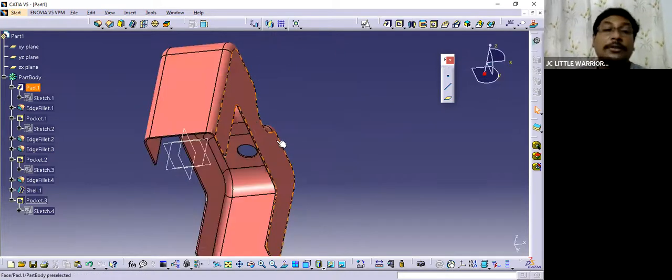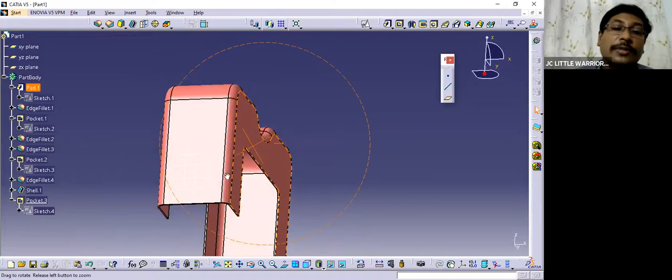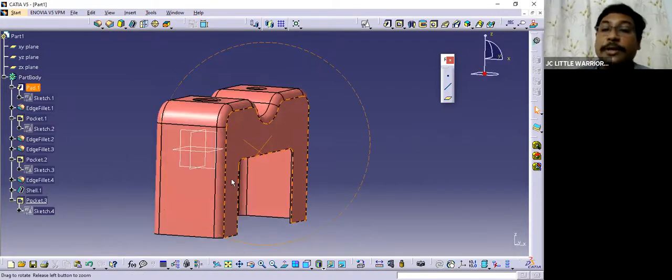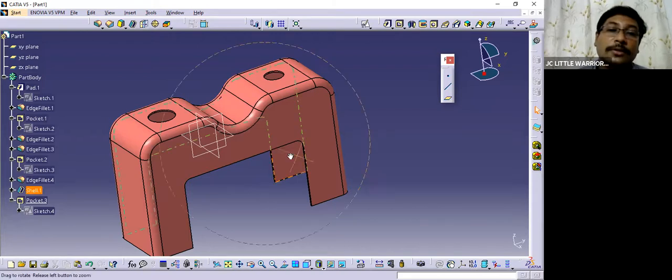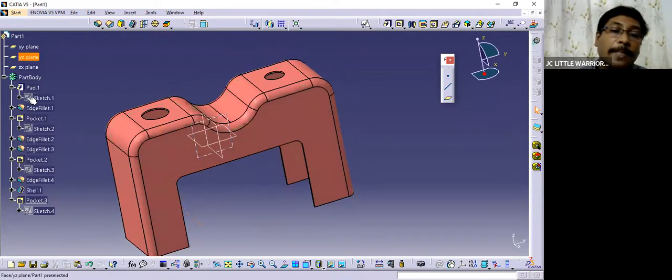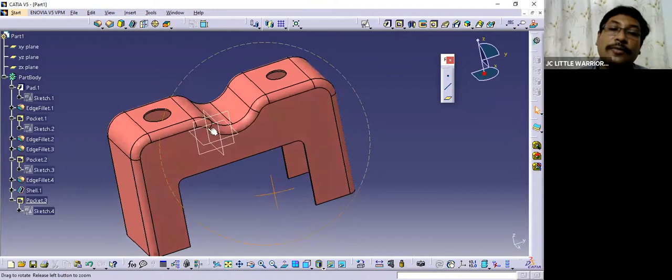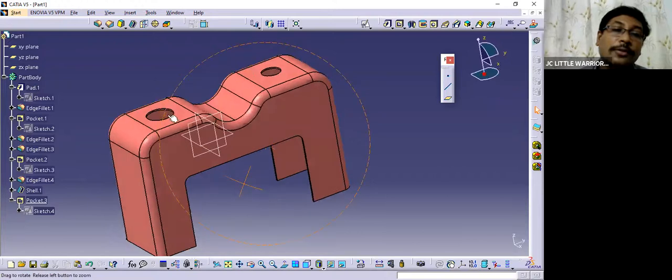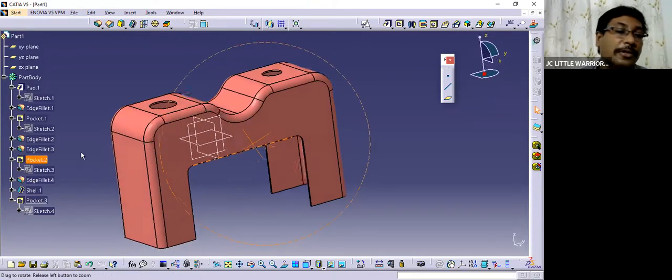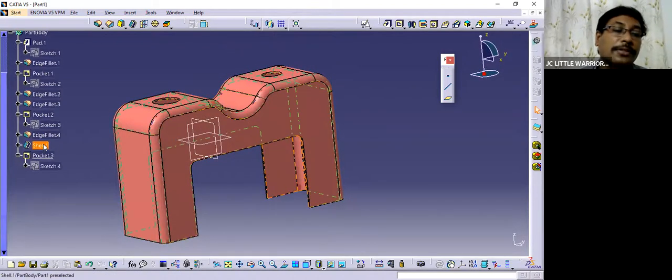Now, most of the parts we did were machining parts. What we modeled are machining parts, and the process we followed was for machining parts. If it is a sheet metal kind of part, then we have to follow this kind of process. So you have to create a pad, and some operations you have to finish beforehand before applying. Even these holes you can finish beforehand. So this you can reorder.